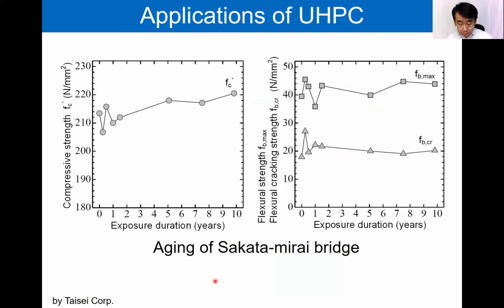And this graph refers to the test results of Sakata Mirai Bridge after 10 years. The compressive strength tends to increase slightly. And the flexural cracking strength and the flexural strength are almost unchanged.